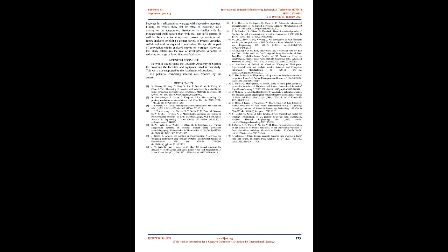It will be beneficial to incorporate convex optimization into future analyses involving a greater variety of process variables. Additional work is required to understand the specific impact of convection within enclosed spaces on warpage. However, this study establishes the role of infill process variables in reducing warpage in fused filament fabrication.